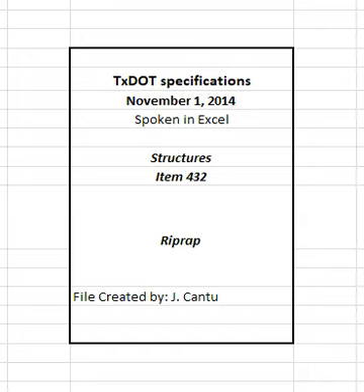Provide a minimum 6 inches lap at all splices. Provide horizontal cover of at least 1 inch and no more than 3 inches at the edge of the riprap. Place the first parallel bar no more than 6 inches from the edge of concrete. Use approved supports to hold the reinforcement approximately equidistant from the top and bottom surface of the slab. Adjust reinforcement during concrete placement to maintain correct position.